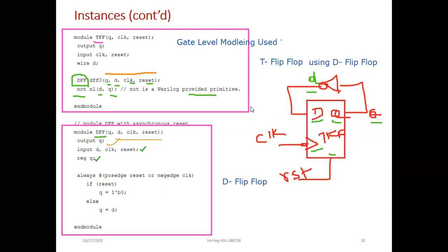Then now let us write it in the behavioral model. Here we use the behavioral model because it's very simple. Now here we use always @(posedge clock or negedge reset). Very important. You see here it can work. Your clock is posedge or reset is negedge. It's asynchronous actually, because you are writing an asynchronous counter, right? You remember the asynchronous counter, we need to use it like this, posedge or negedge reset, because the reset will happen either during the edge of the clock or not on the edge of the clock. That is the reason we have to use posedge or negedge reset.